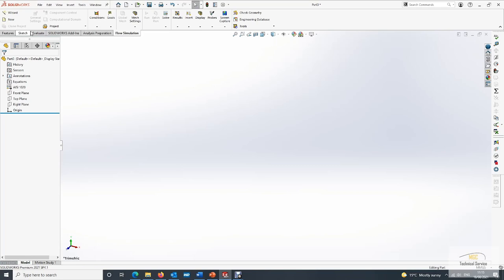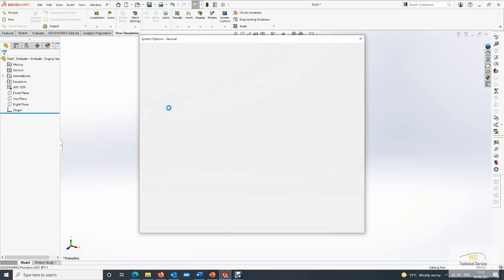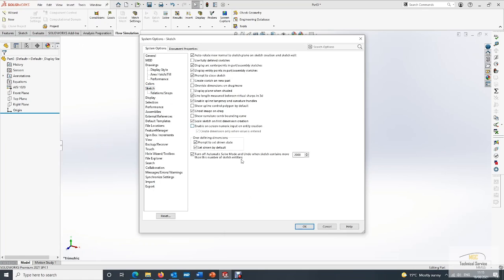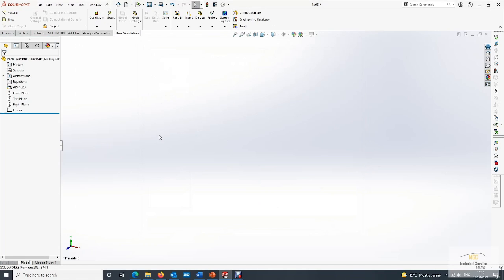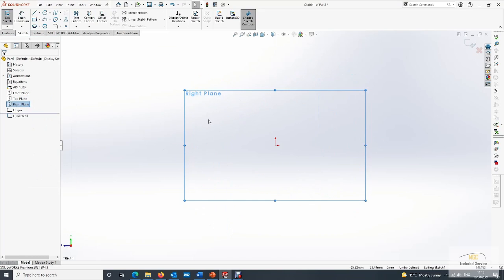Okay, and then there's a tool that I use in the options. I'm going to actually switch it off just now to show you the benefits of this. I find it quite beneficial for saving a couple of clicks here and there. So what we'll do is look at an example. Start a sketch on the right plane. So right click, sketch, and draw just a basic line here.